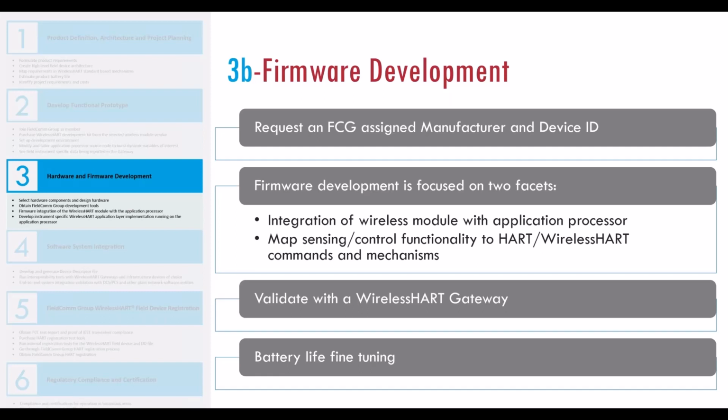But it is your application processor, and the sensors that you connect to this application processor, that will ultimately dictate the battery life of your instrument, because your application processor needs to wake up and interact with the sensor or sensors or actuators, which in turn also draw current.